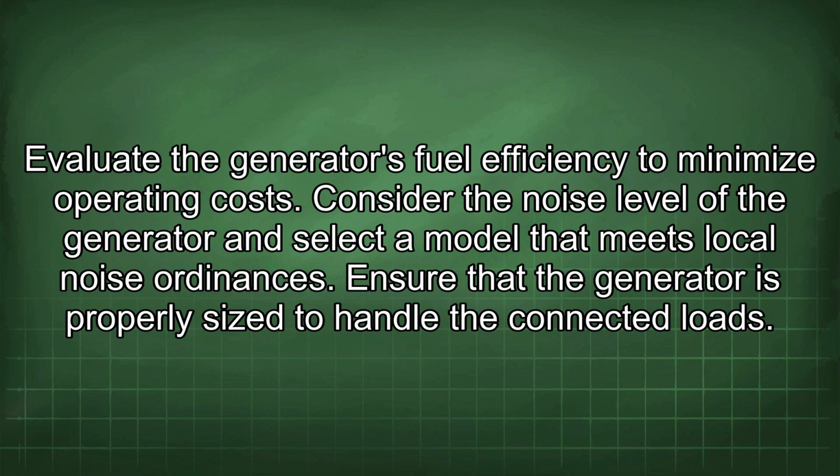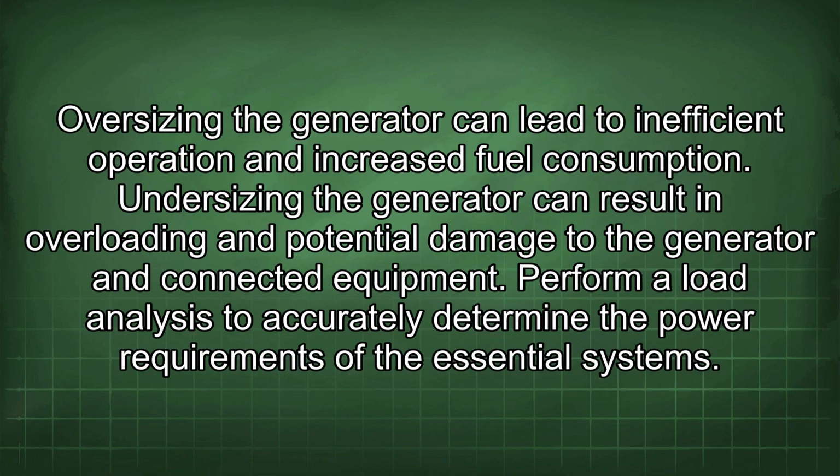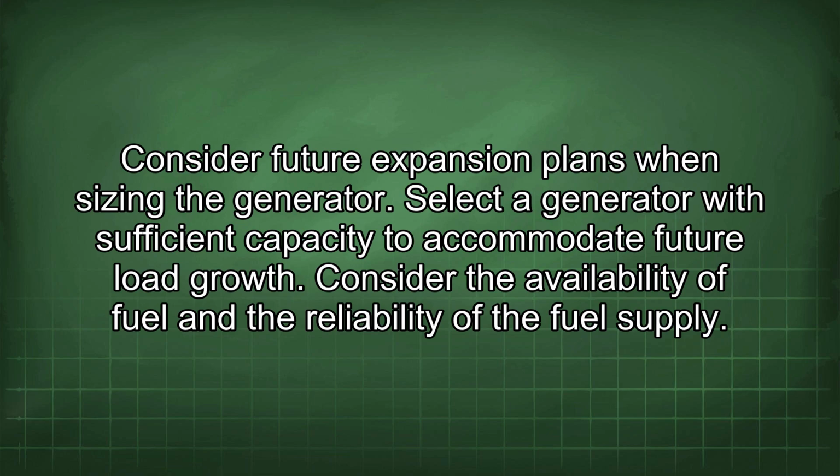Ensure that the generator is properly sized to handle the connected loads. Oversizing the generator can lead to inefficient operation and increased fuel consumption. Undersizing the generator can result in overloading and potential damage to the generator and connected equipment. Perform a load analysis to accurately determine the power requirements of the essential systems. Consider future expansion plans when sizing the generator. Select a generator with sufficient capacity to accommodate future load growth.